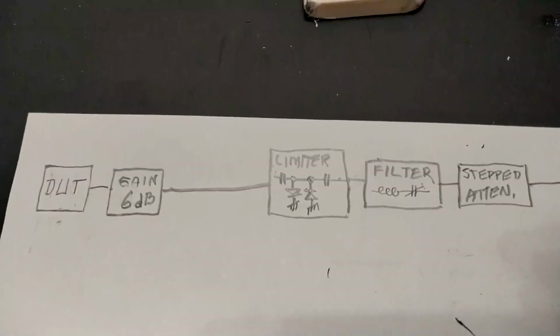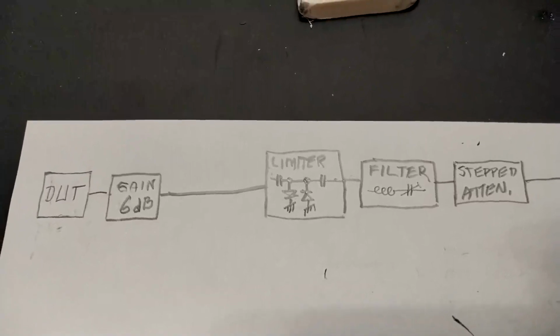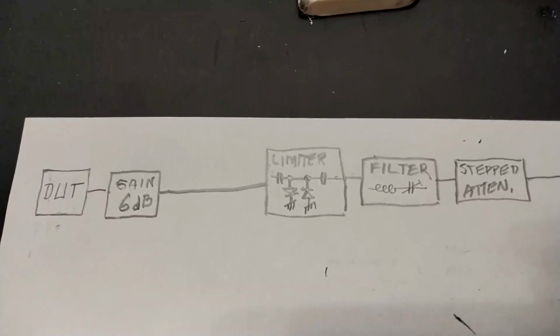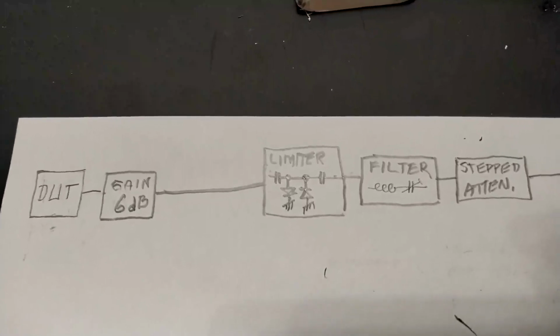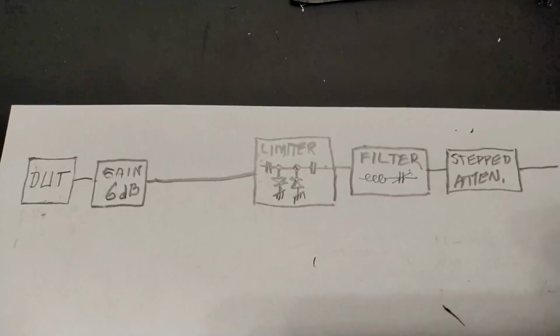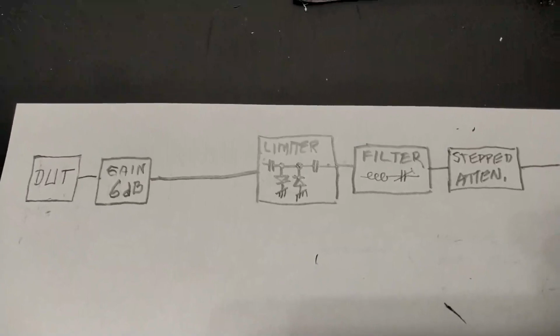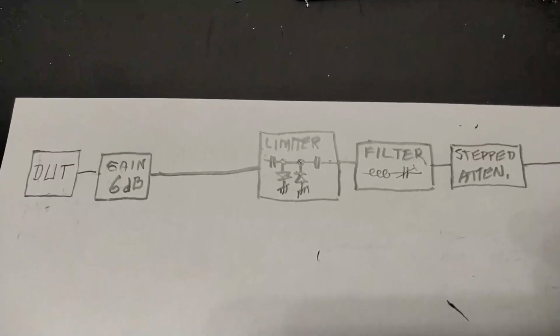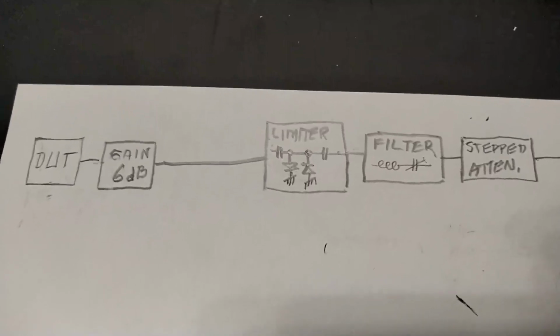I have added an amplitude limiter like this. First amplify a bit and then cross 1N4148 diodes. And then a series resonant filter. It is not tuned exactly on the resonance, it's tuned a little bit off because that optimizes the performance.